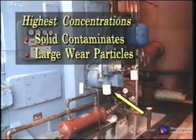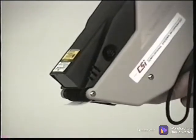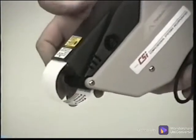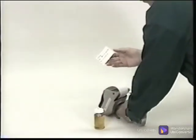However, this is where you will find the highest concentration of solid contaminants and large wear particles. If the filter is free of metallic debris, it is unlikely that much wear has taken place since the filter was last changed. Label each sample bottle with the oil type, the machine from which the sample was taken, and the sampling date. If a sample is diluted prior to testing, the label should reflect that fact.